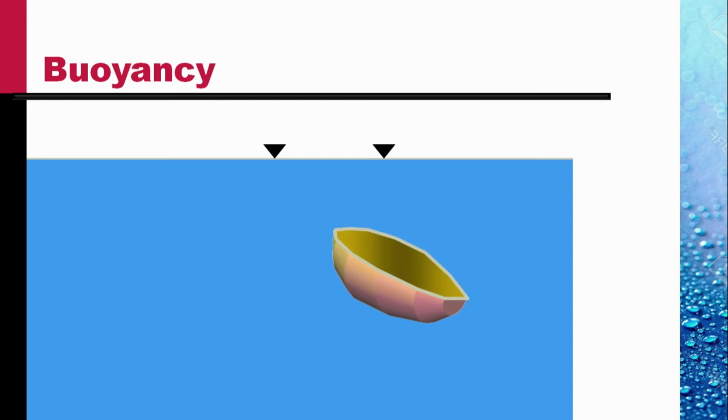The vertical force acting on the bottom half, which will act upward at the bottom, is equal to the weight of the water supported, or weight of the liquid supported by this. So, weight of the darker blue column of water up to the lower half surface. This is of course acting downwards on the liquid, and so it is acting upwards on the surface shown.